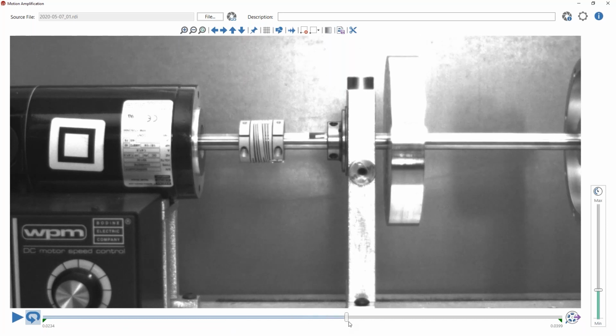The last thing I wanted to mention in relation to a strobe is that if you move away from the asset, there's no consequence. With a strobe, as you move away, the light diminishes. If you've ever used a strobe, you know you have to be pretty close to be able to see it. You don't have that issue here with shaft inspection. Again, I just wanted to demonstrate that, because this is a really easy way to capture this and record it, and also have it for recall at another time.